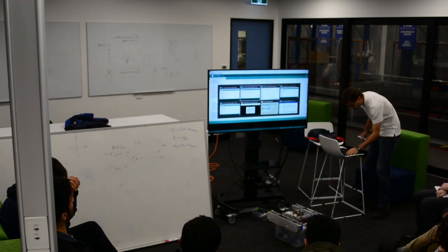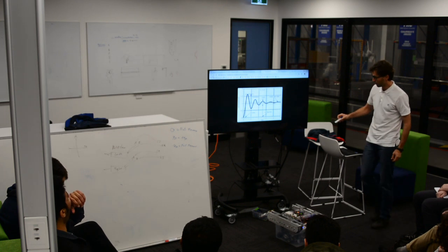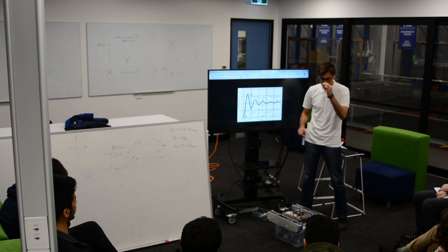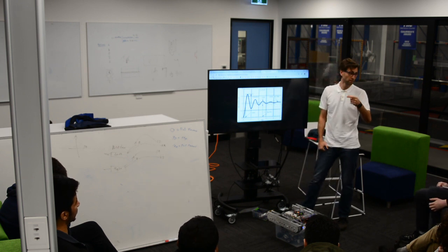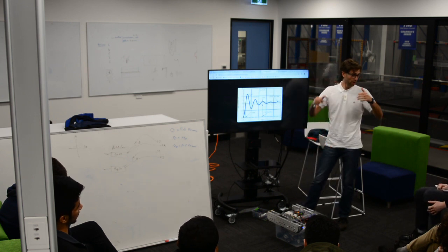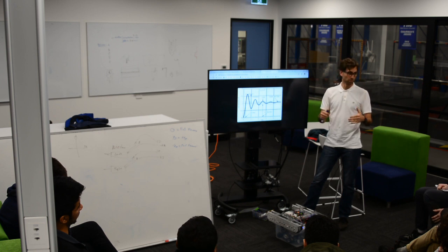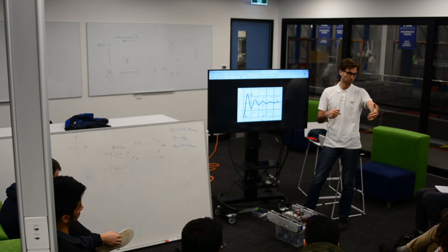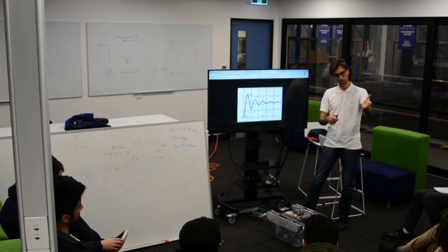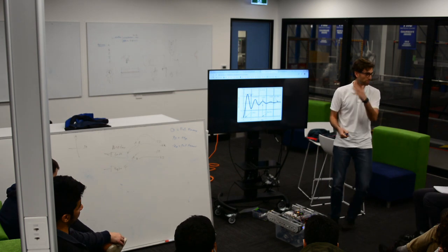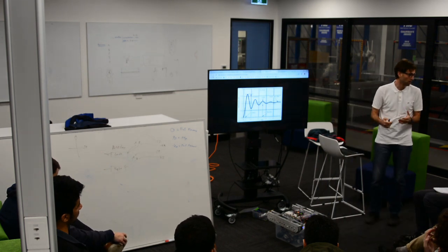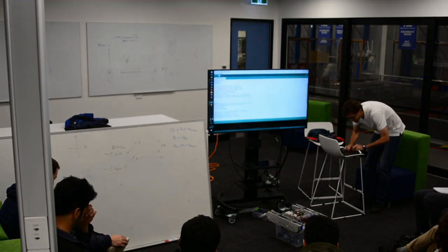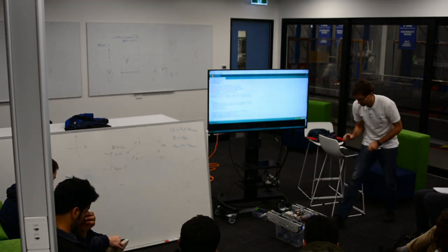The reason it's going to go apeshit is if we go back to this picture here. This is where we'd like to be, and as we approach that, even if we're 1 millimeter away from our desired position, we're still going full throttle, 100%. So we're always going to overshoot. We're going to blow past our target position. Then our computer's going to go, oh, you're on the wrong side. Full reverse, try and go back, and it's just going to, bang, bang. That's why they call it a bang-bang controller or an on-off controller, right?